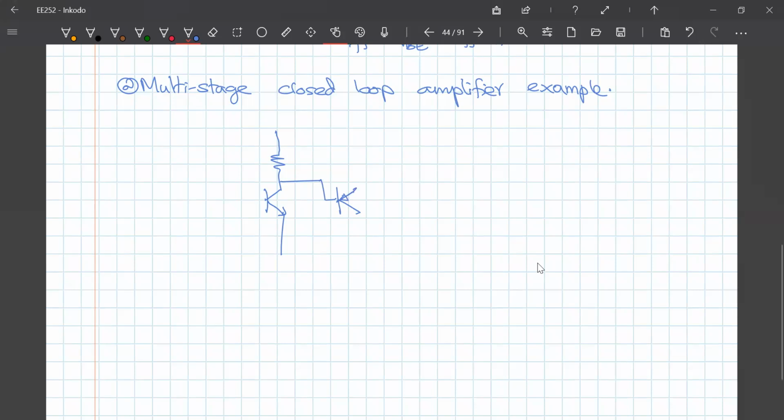The first one is NPN, second is a PNP, so that you achieve this temperature stabilization or temperature desensitivity due to varying VBE dependence. Okay, so this is the emitter. So this is a common collector. So you have the resistor connected to the emitter, not the collector. Right. So this is like that.